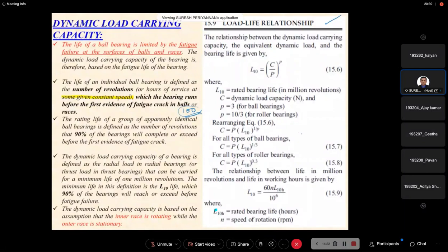Sorry. Okay. So first we already predicted the ball bearing life is 100 million revolutions. But when we are performing the testing using these methods, ultrasonic, thermographic or X-ray, then at 99 million revolutions we identify the first crack on the bearing.